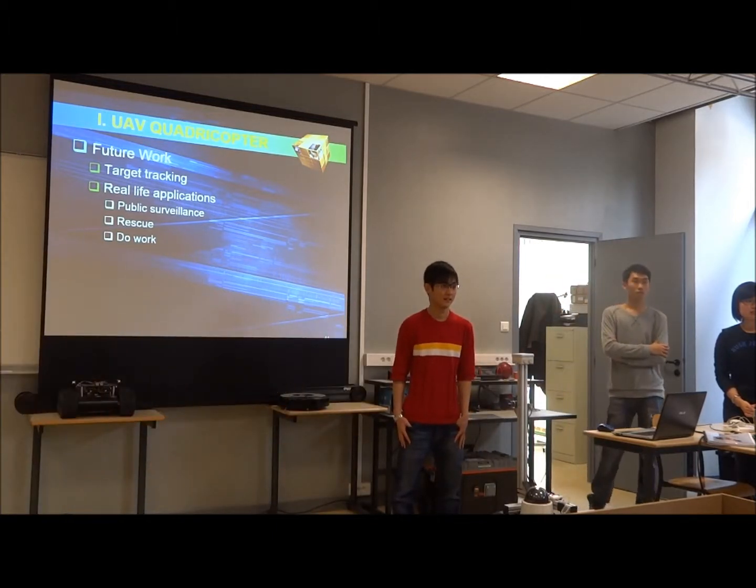How do you compute the distance from the target? The distance itself, as I mentioned, since the drone has only one camera, so it needs to be moved in order to recognize the distance. So it takes one location, and then it moves up, like probably 1 meter. So the area that is overlapped, the distance will be computed.